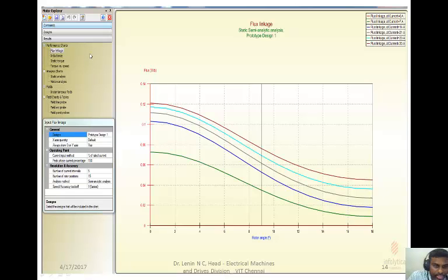So the first thing is flux linkage. I just click the flux linkage and plot the result. You may refer to my previous lectures so that it is easy to understand how to do those steps. As far as that figure is concerned, I analyzed for a peak phase current of 100%, that is 100% peak current, with a current interval of 5. Number of rotor positions is 15.